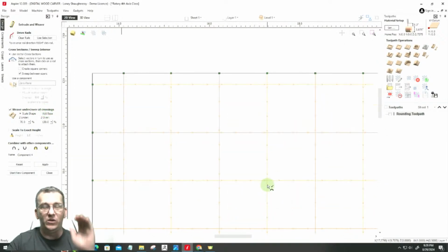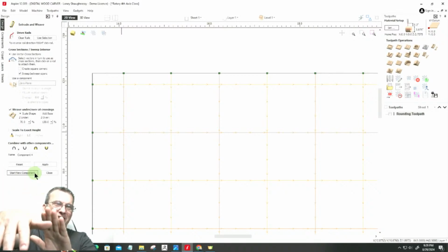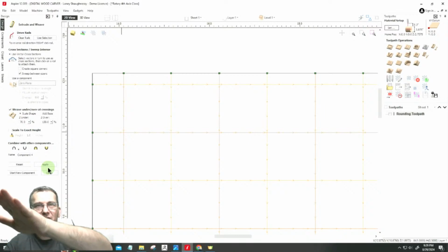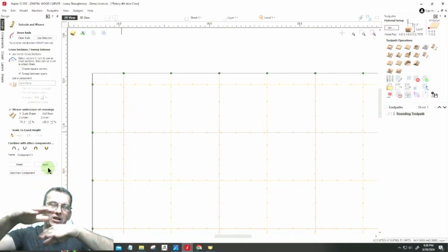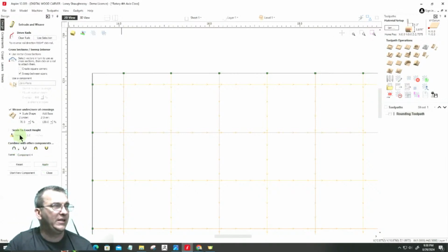I want that to weave over and under. And I have options. I can go under by 70% of my shape, over by a certain percentage. And in this case, I'm going under. On the Z, I'm reducing it by 70%, so 30% will be left on 100%. And on this one, that 30%, I'm going on the over. So I've kind of just taken 30% from here and added it to there.